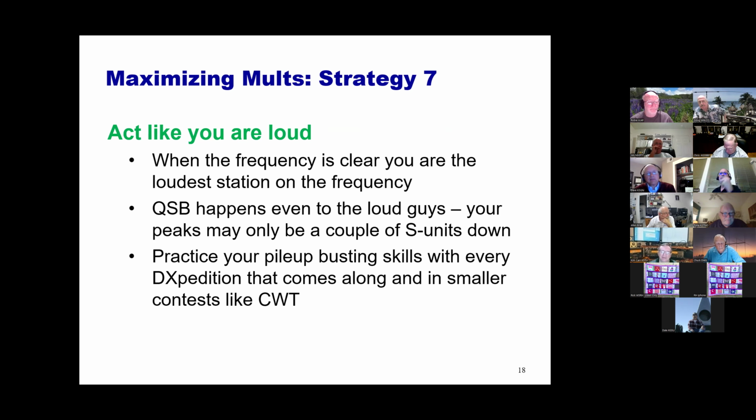But here's another thing. When the frequency is clear, you are the loudest station on the frequency, even if you're running 5 watts, right? So if there's propagation enough for them to hear you at all, and nobody else is calling, you're the loudest station. So act like it. Don't act like you're weak. Act like you're loud. That doesn't mean you're not going to apply the skills of knowing just when to call, as opposed to just slamming your call in there and expecting them to come back because you're a big gun. But remember that when nobody else is calling, you're loud.